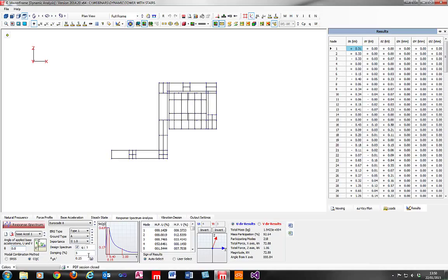Just like in vibration analysis, whereby you get a square root sum of the squares of the acceleration that occurs due to the various different mode shapes, seismic response is quite similar in that we're going to combine forces for lots of different mode shapes, and the way in which we combine those forces is determined here. The complete quadratic method is a more sophisticated method which is recommended these days.